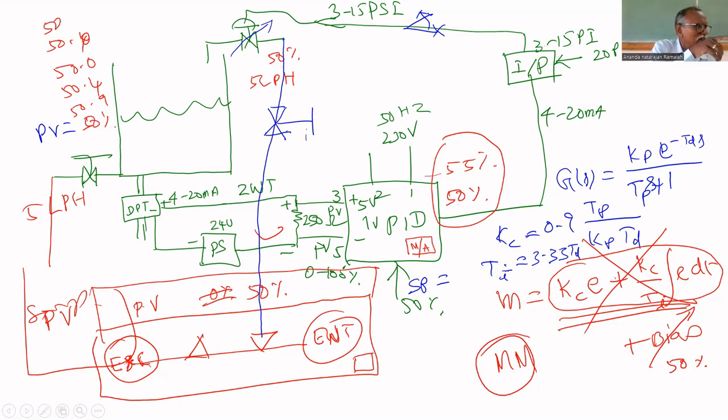The display will change between set point and manipulated variable. So you have to press auto manual at that time. Three conditions satisfied: process at steady state, set point equal to PV, and correct tuning parameters entered. Now you transfer auto manual. The process will be in auto mode. It means any disturbance comes, the controller will take care.